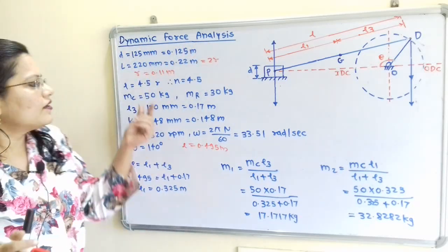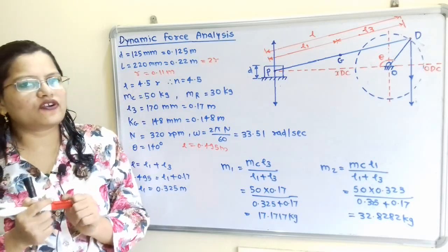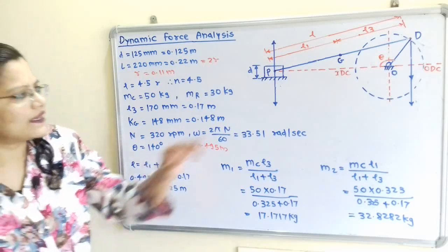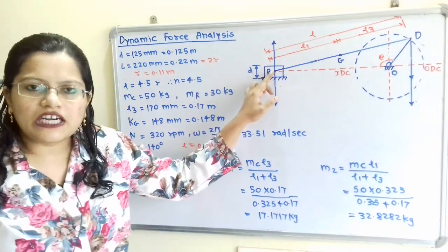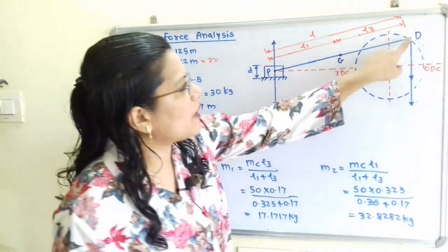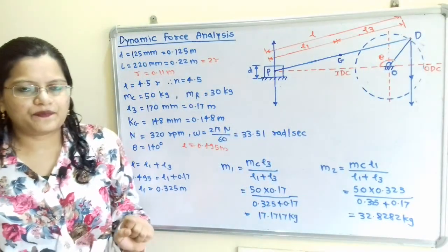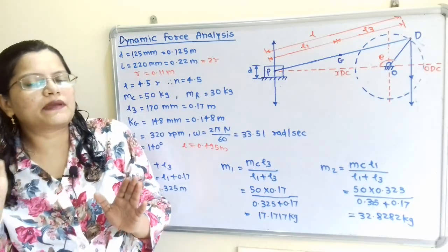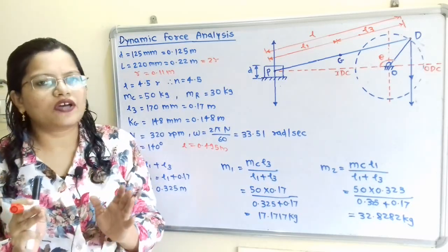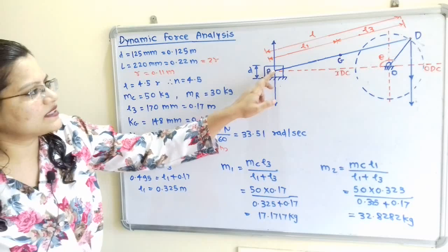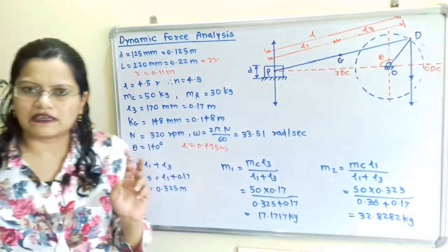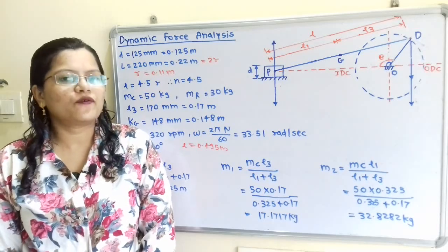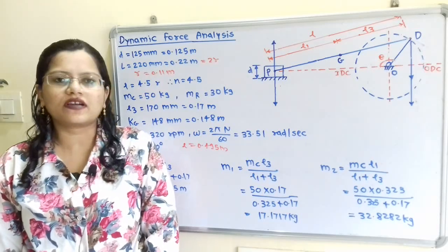And when we split this mass of connecting rod, that is into two masses M1 and M2, and we have to place the mass M1 at this gudgeon point P and mass M2 at this crank pin D. Then the system will become non-dynamically equivalent system because we have to place these masses M1 and M2 arbitrarily. For this non-dynamically equivalent system, we have to apply the correction couple.